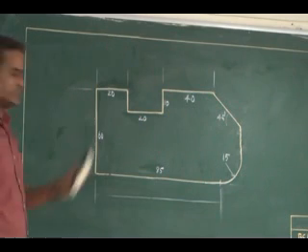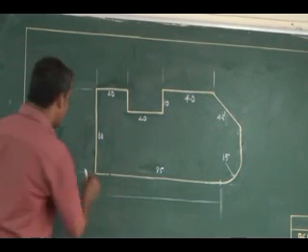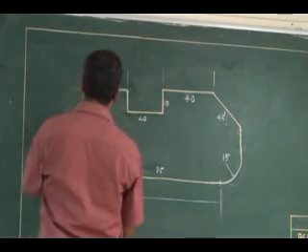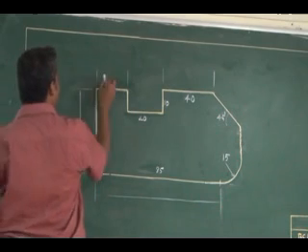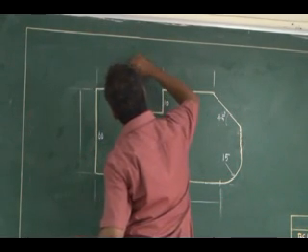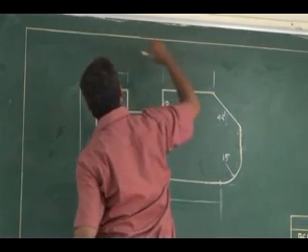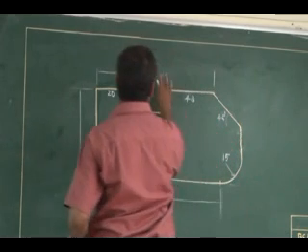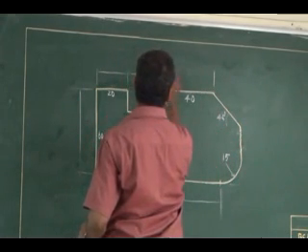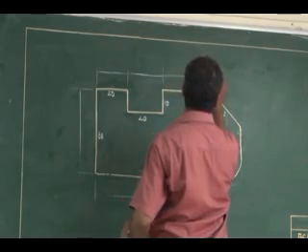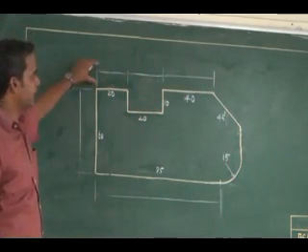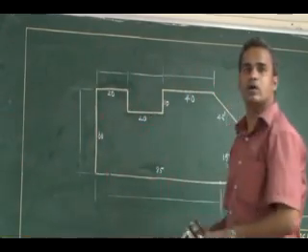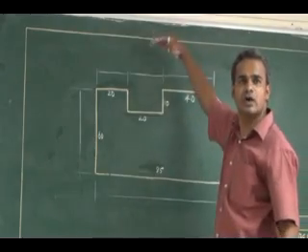Now, for this extension line, the dimension line should be parallel to the object line. Similarly, the gap should be maintained. So I have 3 dimensions. You should not dimension them separately, in a different location.